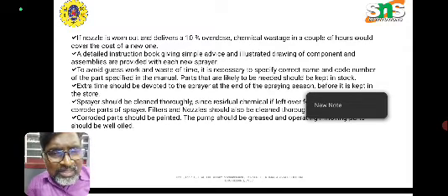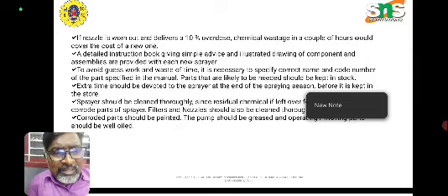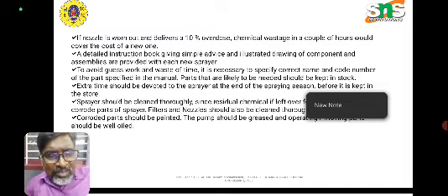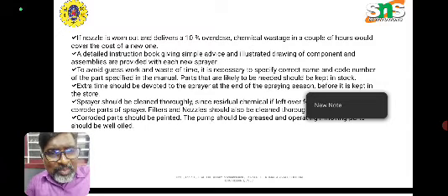That means if the nozzle is not maintained properly, then what will happen? The application of these pesticides or chemicals that we are going to apply will increase by 10 percent. That means an overdose of only 10 percent. When we calculate the chemical wastage in a couple of hours, say 2 hours, it would cover the cost of a new nozzle. That means instead of buying a new one, such a high cost will be involved if we do not maintain the nozzles in a proper manner.